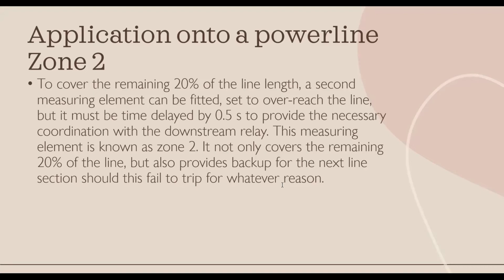It not only covers the remaining 20% of the line, but also provides a backup for the next line section, should this fail to trip for whatever reason.